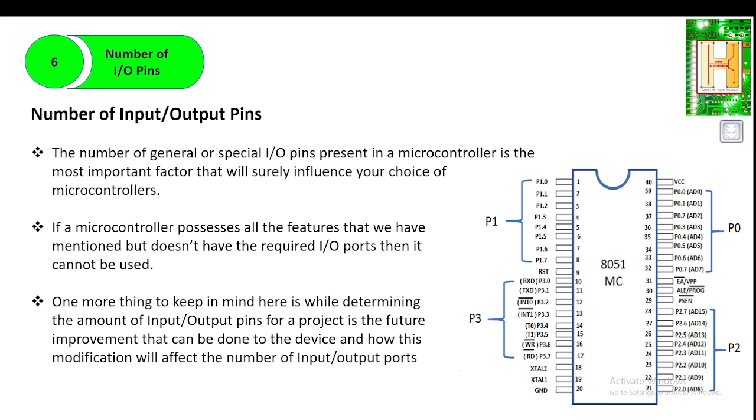One of the most important things that a designer should decide is the number of IOs which they are going to use at present, and some IOs should be kept spare for future implementation, if they want to add some advanced features or modify some of the project's input and output. It should not happen that at present you have selected a microcontroller based on the number of inputs and outputs, and in future if you want to add additional features to the system, the IOs are not sufficient. So the designer should always think ahead of time.